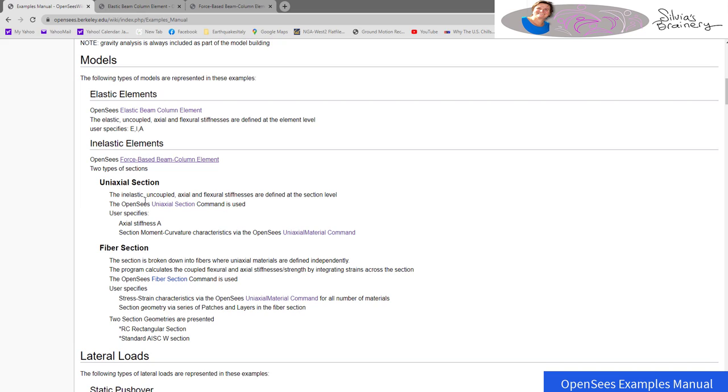What really matters in a fiber section is the variation of axial load during your time series or your analysis. If the variation is not significant enough, then you don't need to go to that. So you would use it in columns, especially outer columns, because then your corner columns could also take into account the interaction between bending in two directions.